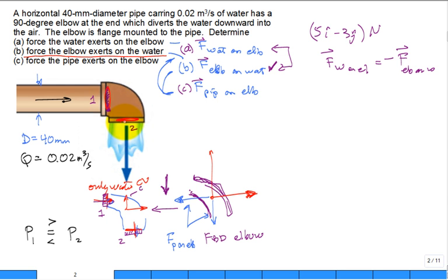And the consensus is that they're equal. Why are they equal? They don't change speed and they don't change area. Yeah. And so who wrote Bernoulli's equation and went from 1 to 2? Didn't you deduce then, because of the non-change in area, the density or the specific volume is the same, hence speed is the same. Neglect the effect of gravity, a little hydrostatic, forget it. Don't worry about the rho g z.